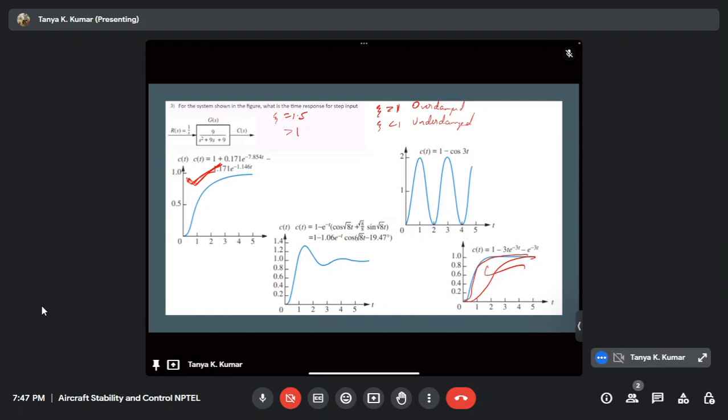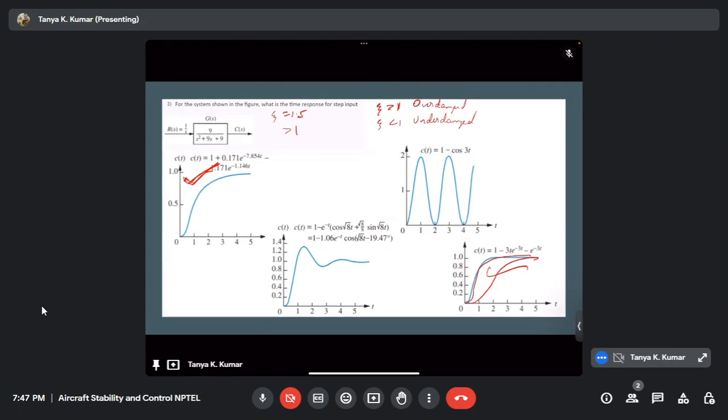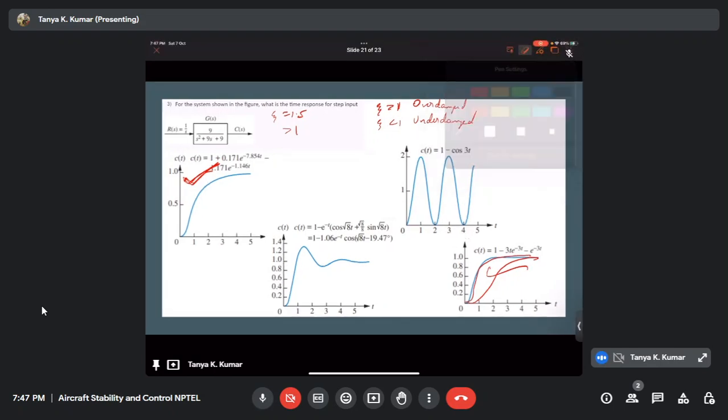But okay, I've put 2 ticks. Just give me a minute. I'll just write this neatly. Okay. So from our damping ratio, we know it's either this or this. Now the overdamped and critically damped, if you just compare the two graphs, it's something like this, right? So for our overdamped case, this is the right graph, okay?